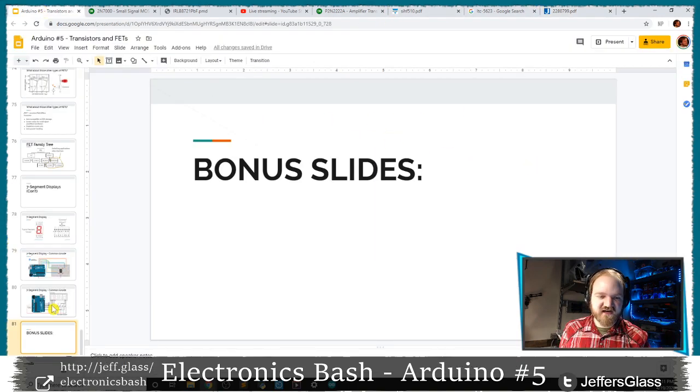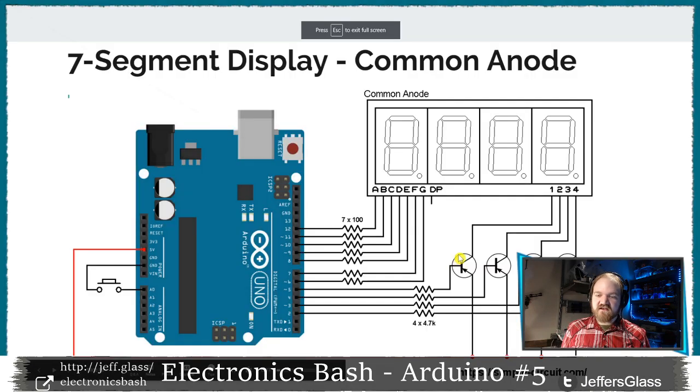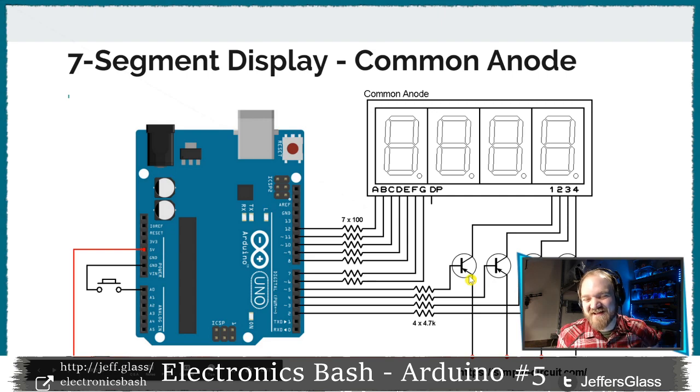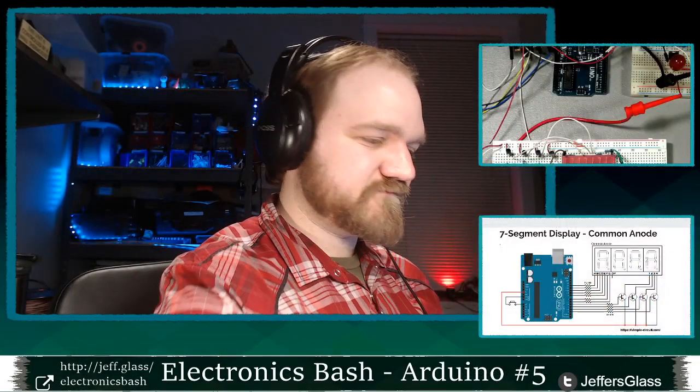To go back to our circuit diagram, what we're going to do here is use these PNP transistors. See, I told you transistors would tie back into it. We're going to use these PNP transistors to selectively apply that positive voltage to a specific anode pin for digit 1, 2, 3, or 4, and then selectively ground the cathodes for that pin just for that digit. So if that's not quite making sense yet, let's jump in the code, and I think it will.